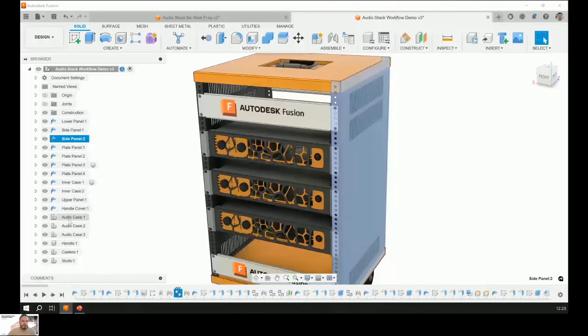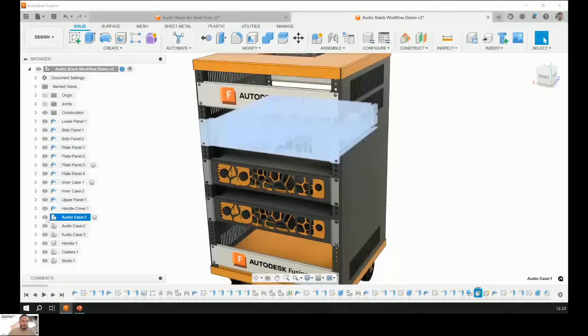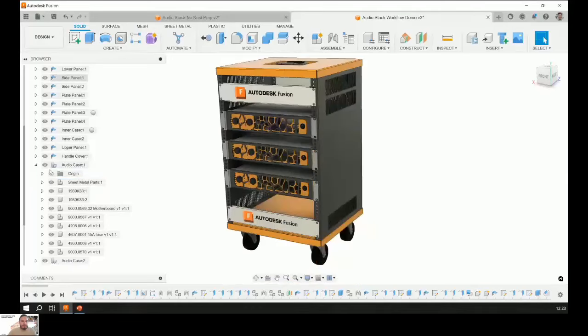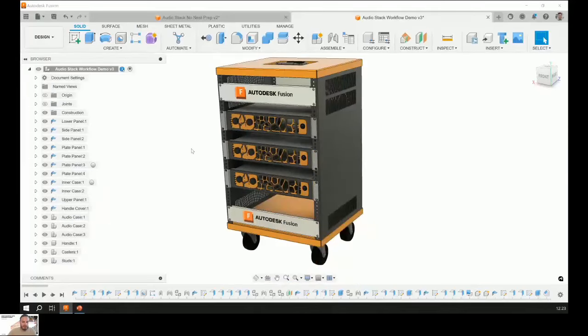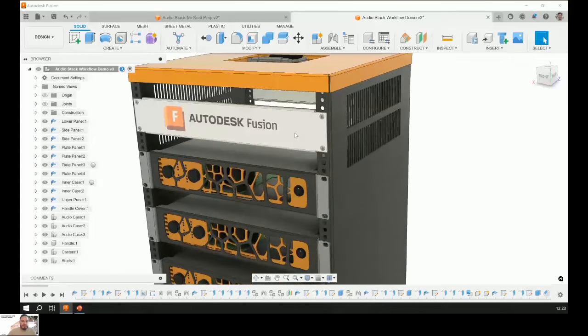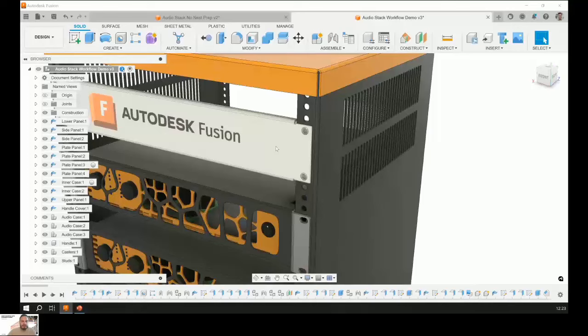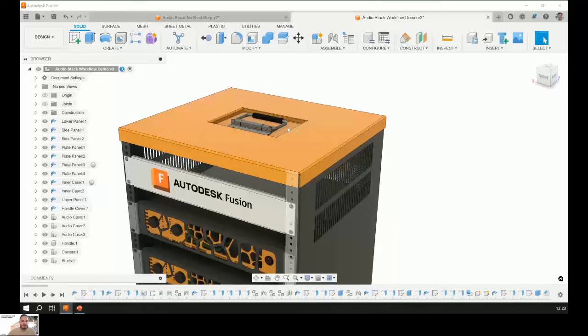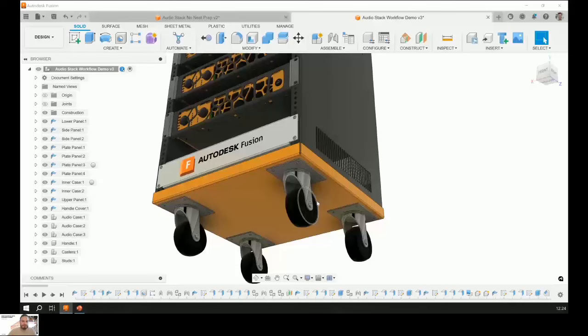It's also organized in a couple of sub-assemblies that also, again, have sheet metal parts inside. Now, if we look at this whole assembly, though, I would probably not want to nest all of the parts out of this assembly, right? So obviously the sheet metal parts, they make sense. But if we look at the fasteners that are part of this assembly, or let's say the handle up here, also the casters, this is not necessarily something that I would like to nest.